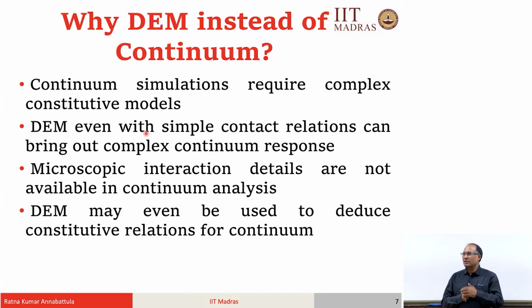Another important aspect, the main difference between a DEM simulation and a continuum simulation, is that through DEM simulations we can get access to the microscopic interactions. When I say microscopic interaction, I am talking about what is happening at the individual particle level. Although as an engineer you are interested in the macroscopic behavior of a granular system, that macroscopic behavior depends on what is happening at the micro scale, that means at the particle scale, and that is something that we can naturally get through this method.